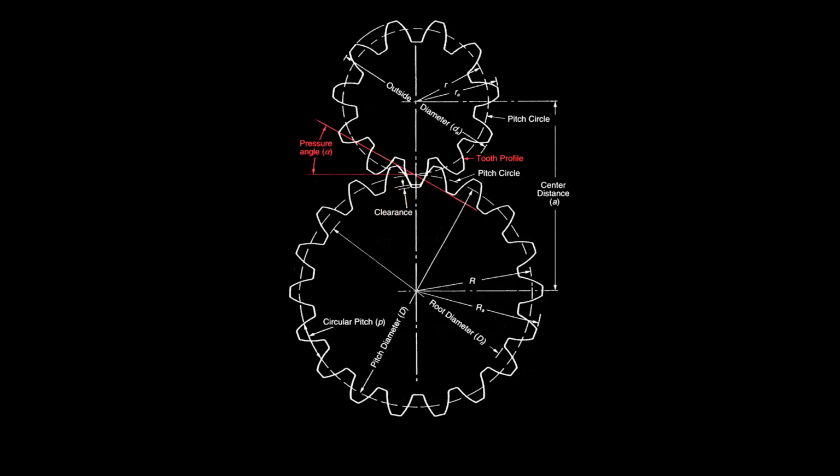When two gears act on each other, the touching surface is at an angle, namely the pressure angle, and it is standard 20 degrees for modern gears. The pressure angle can be measured over the line perpendicular to the center line. Tangent to the line of action are the base circles.